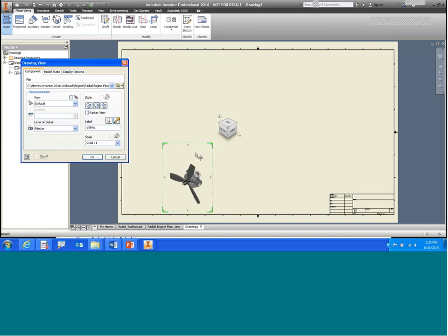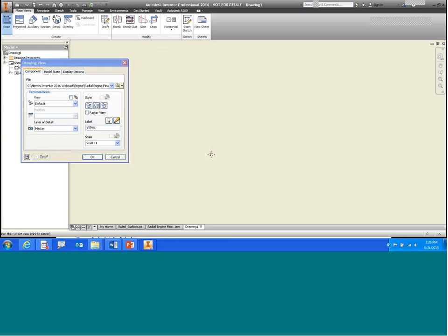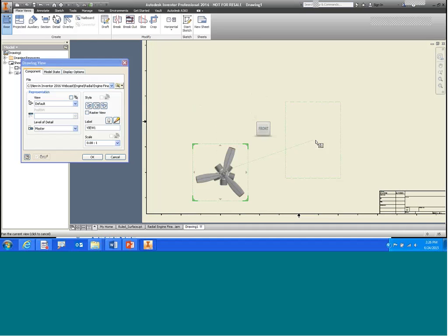Now, if you look right in that preview that I am looking at here, you can see I've got this view cube now in my drawing. So what I can do is, just like in any 3D modeling environment, I can actually select on edges, and it reorients my model completely, so my view. So you can see how I can flip things around and do everything I wanted to and did in the 2D environment. So I'm going to flip this back and just create my view on the front.